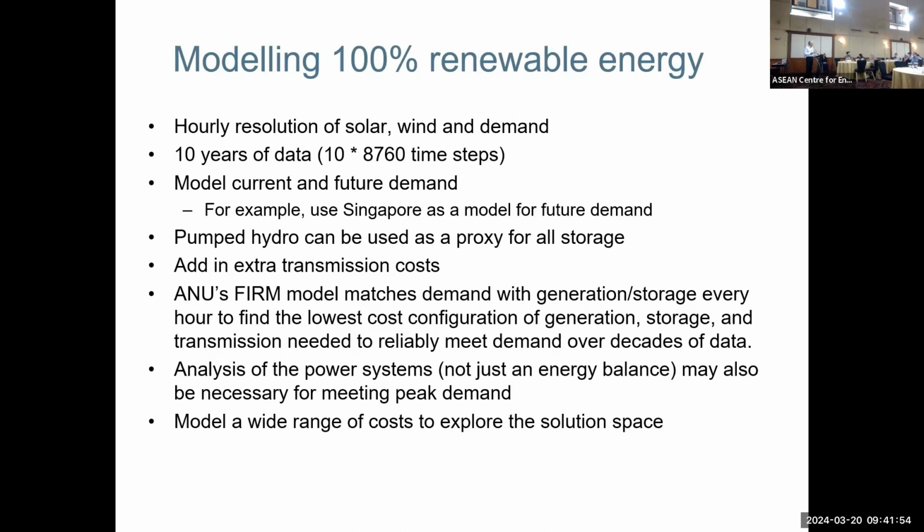So you can use batteries and pumped hydro, but the initial thing to look at is an energy balance rather than a power balance. So you're looking at multi-hour resolution rather than focusing on will we meet the evening peak tomorrow week. You're looking at energy over hours, days, months, years to work out how much large-scale, long-duration storage you need.